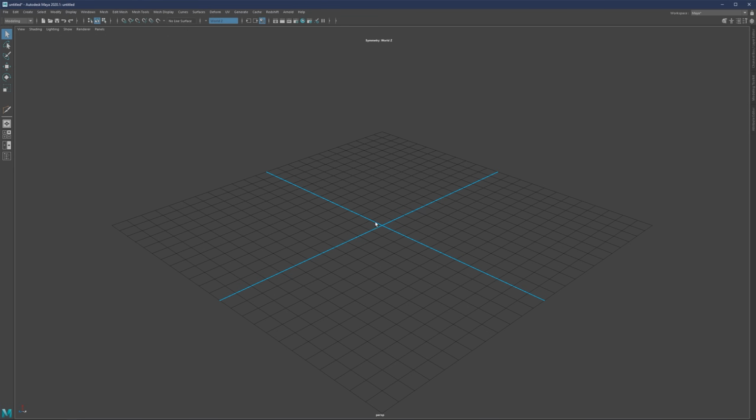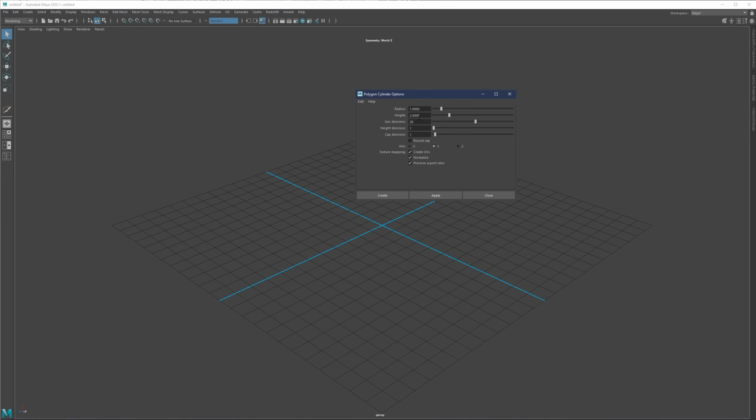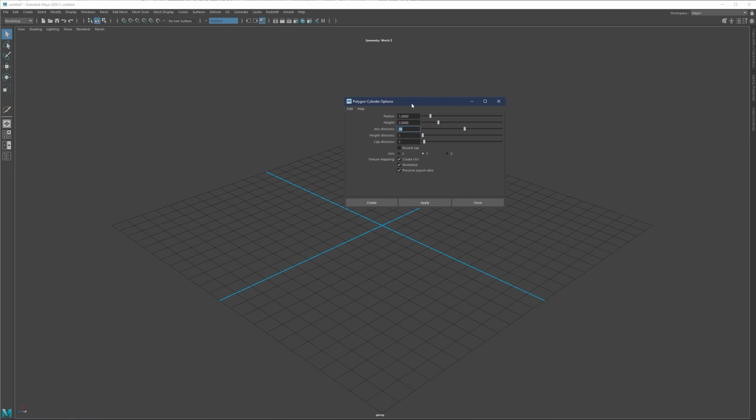All right, let's begin with the first example, and I'm going to use a cylinder, and I think 28 sides is going to be fine. The sides will actually depend on a number of factors. If you don't plan to do any detail or any booleans, you can use even 16, 20, 24. 24 or 28 sides are a kind of golden middle, I would say, if you still plan to do some detailing and you want to have enough geometry.